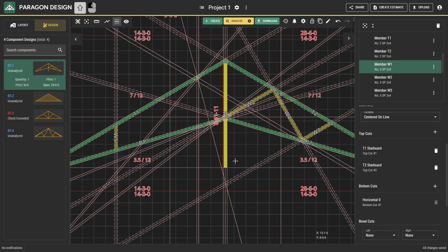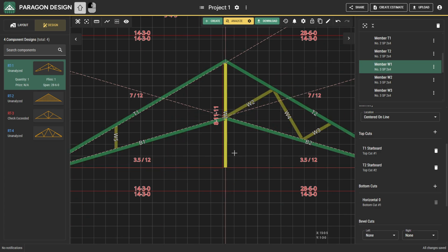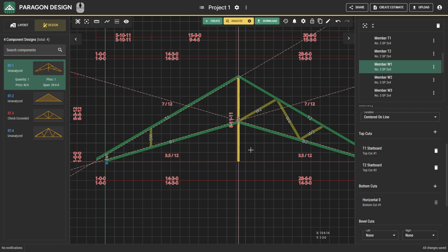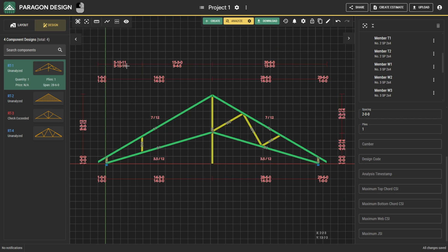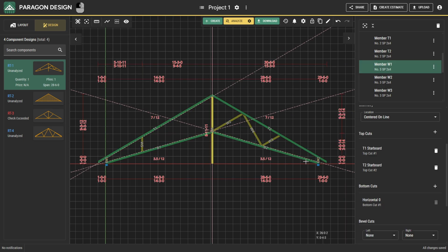Take note, you can always cut member ends against multiple lines. This can be used if you want to double cut a member against another member. The software will try to determine which end you want to cut. But if you need to specify an exact end, click the member again, go here, then click Add on the specific ends where you want to add it.